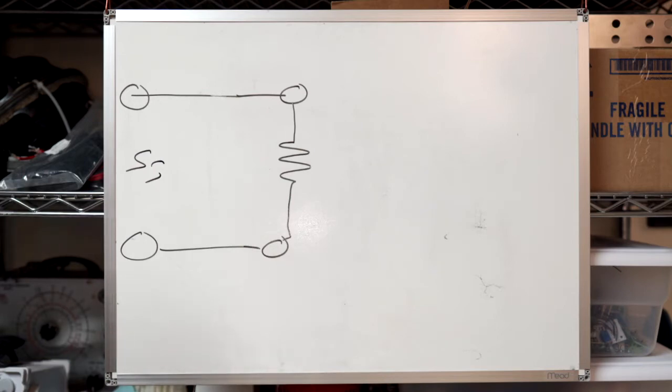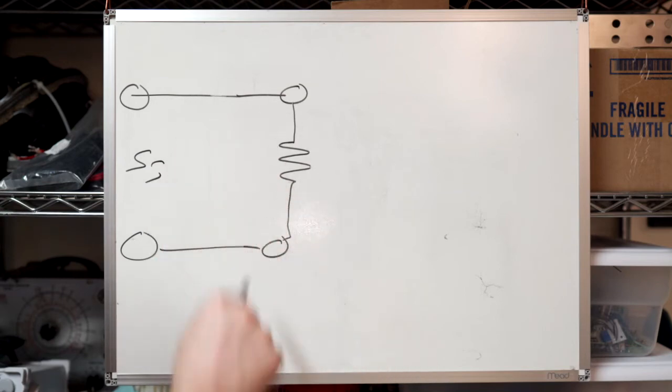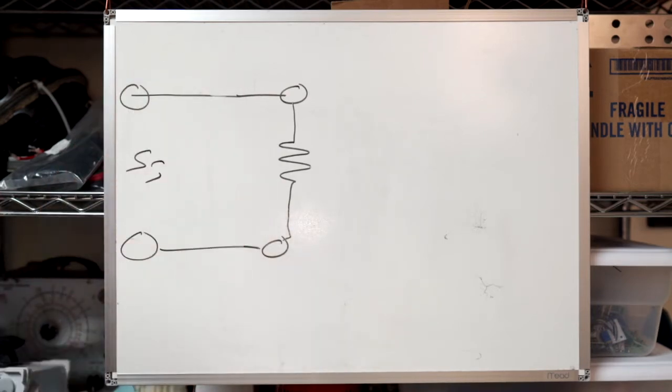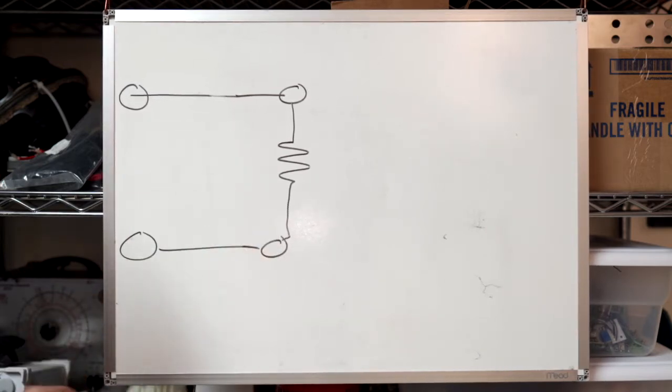Okay, so the output impedance of a solid-state amplifier might be something like 0.5 of an ohm or something like that. And it's only rated to drive perhaps 4 ohms, right? And so if you were empirically trying to find the output impedance, then you would break your amplifier before you found it. And so in that case, you need to measure it in a different way. And I'm not going to go into that right now, how you would measure that. But just know that this is sort of a theoretic understanding of output impedance.